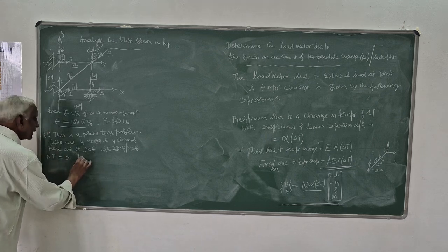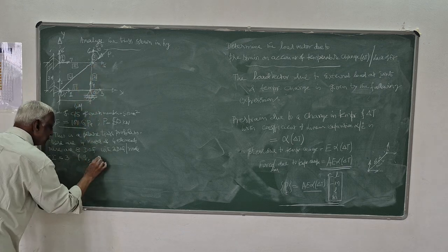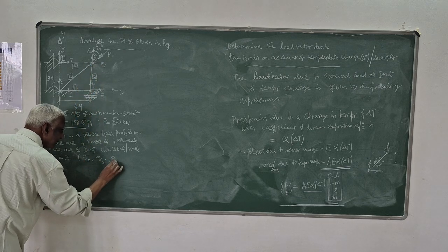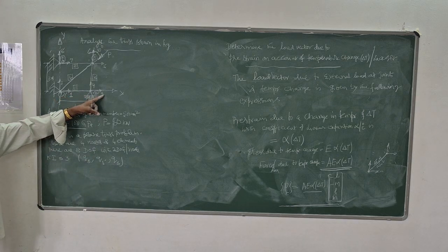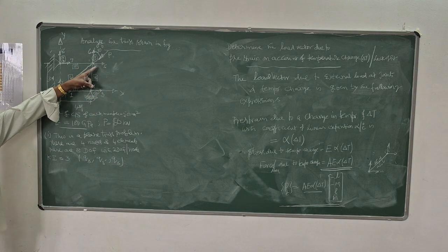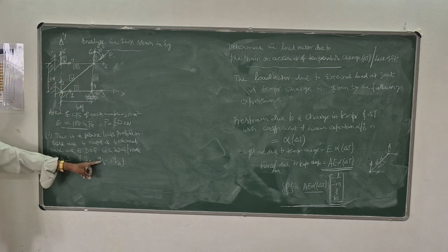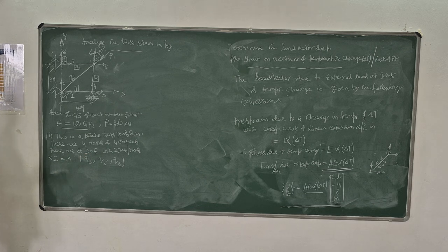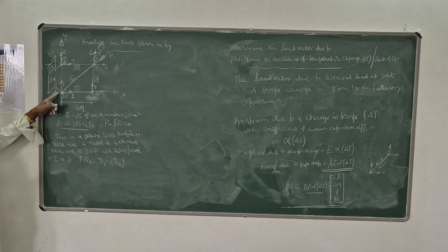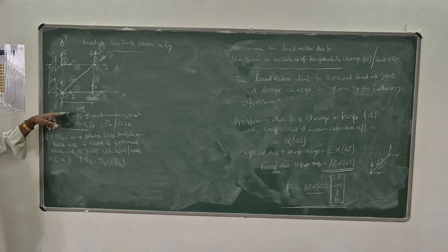So they are nothing but Q3, Q5, Q6. You have to determine only displacement along 3, displacement along 5, displacement along 6. Q3, Q5, Q6 is equal to the kinematic indeterminacy. Each joint has two displacements. Totally there are 8 displacements, that is 8 degrees of freedom.